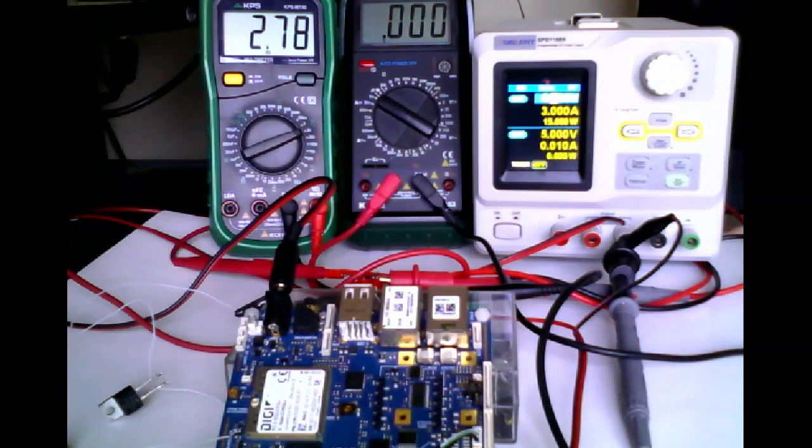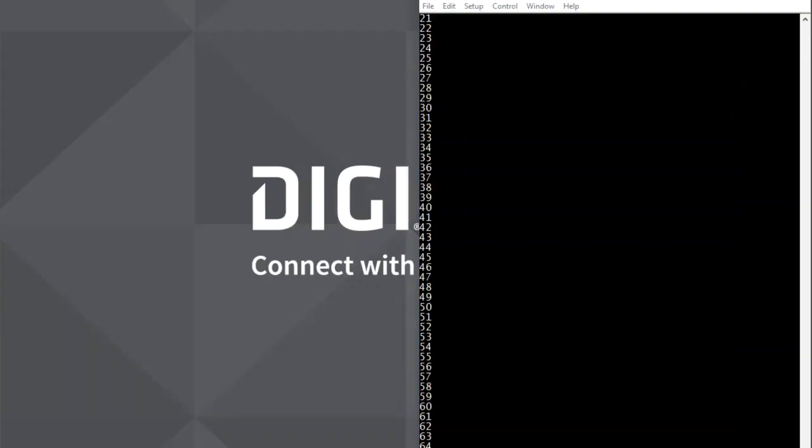Now, if I press again the on-off button, you can see how the system is waking up in milliseconds, and the software, of course, is continuing at the same point where it was stopped. Digi is providing this infrastructure to have several wake up sources. So you can use whatever MCA event and also whatever GPIO on the CPU that you can set up as an interrupt source.